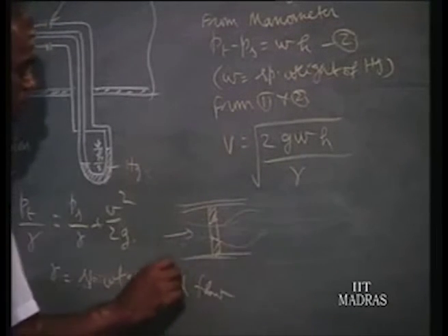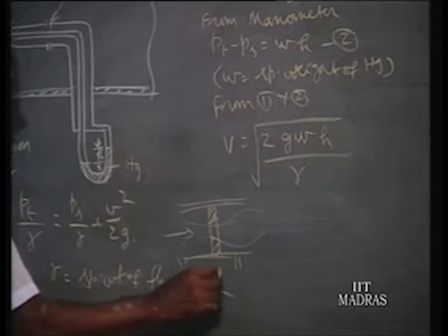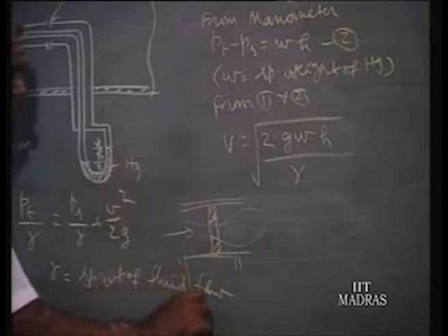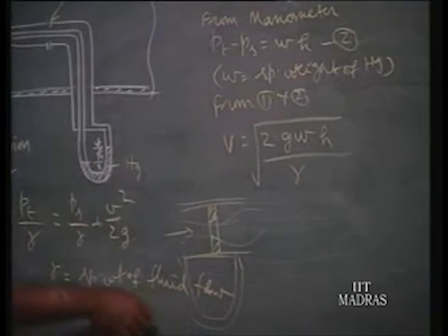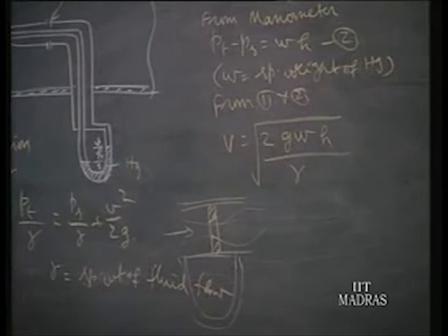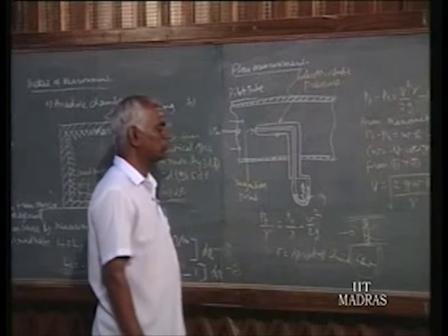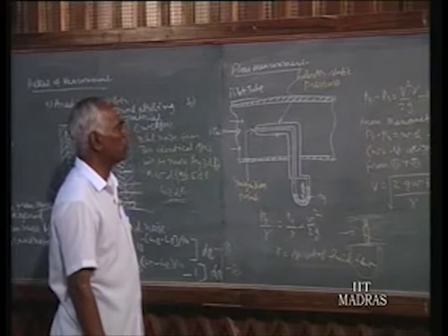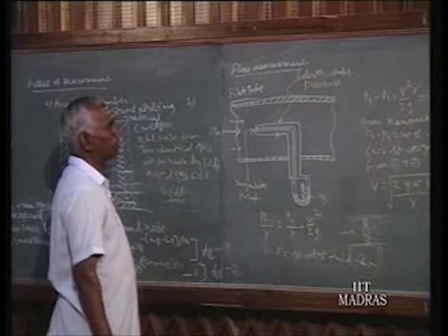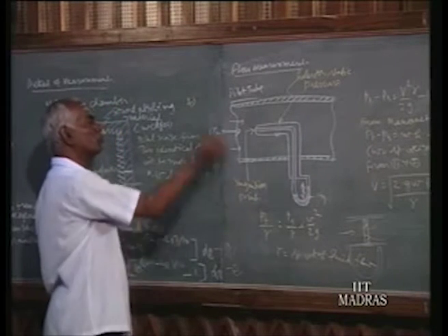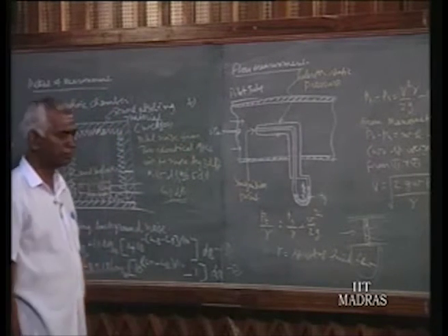We measure the upstream pressure and the downstream pressure at the vena contracta, and then measure with the help of the manometer. These are what we normally learn under hydraulics, and all the positive type flow meters are there to make the measurements. All those things I am not going to do; only a few other special methods used for flow measurements alone we are going to see under this topic, mechanical measurements. First and foremost, we are taking the pitot tube.